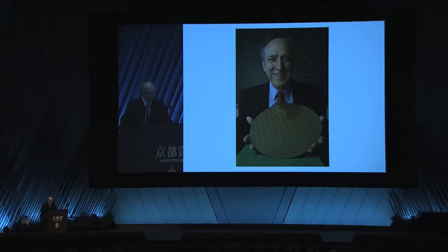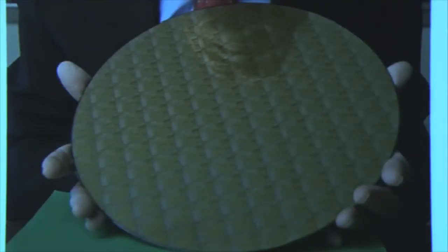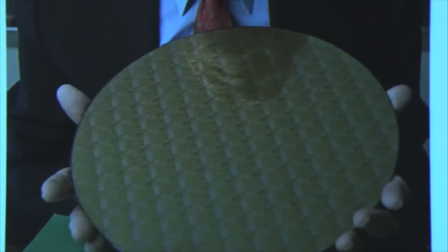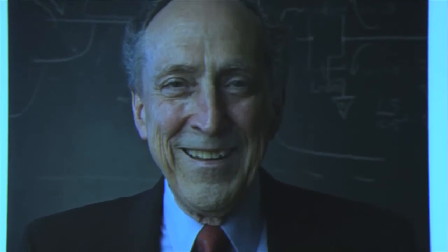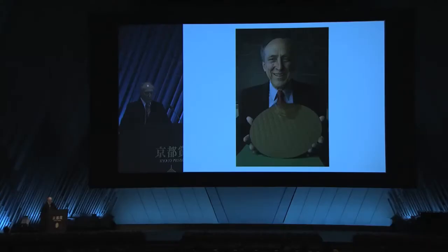The growth in size of chips and the increasing number of transistors and circuit elements on a chip followed the path known as Moore's Law, which is named after Gordon Moore, one of the Intel founders who predicted it in the early days. As the complexity of those chips increased, it became very difficult to implement all the numerous wiring connections among the transistors, the logic circuit inputs and the logic circuit outputs. It became necessary to provide multiple layers of wires. These were organized with all the wires on one layer running perpendicular to the wires on the next level, like streets and avenues in Manhattan in New York.